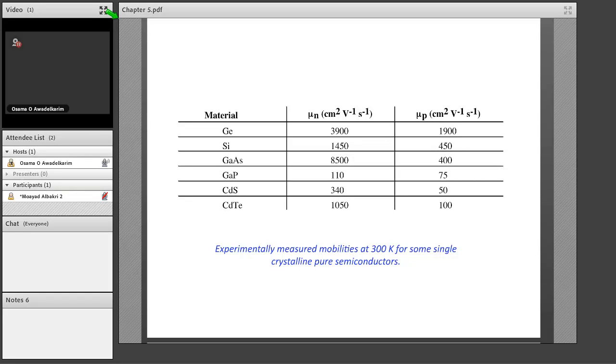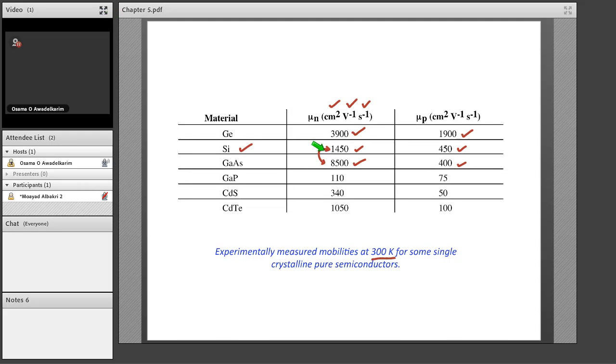of data, and they want very, very fast response to signals. So that is why they used gallium arsenide in these computers. But these are very, very expensive computers because gallium arsenide is very, very expensive to make. And so you see also mobilities in some other compound semiconductors, and you see how they vary.